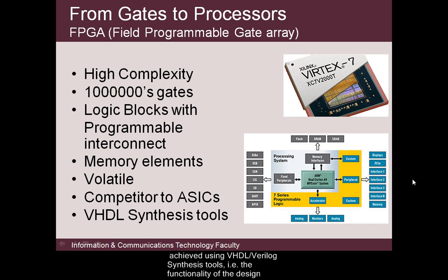They're usually designed using VHDL or Verilog synthesis tools. That is, the functionality of the design is described, simulated and verified in a high-level hardware description language program before being directly synthesized to the chip.